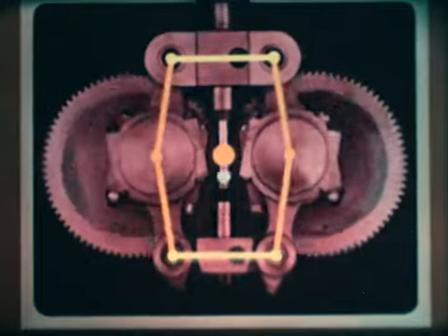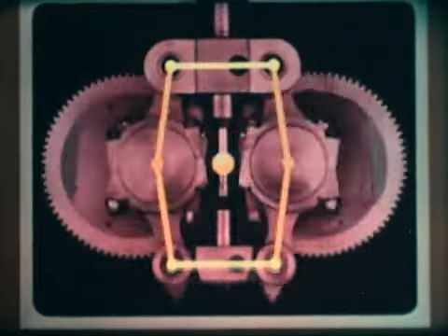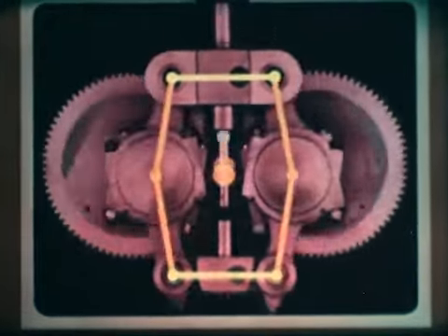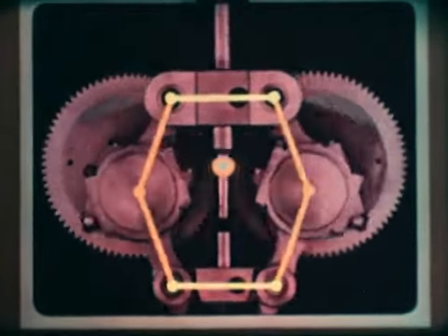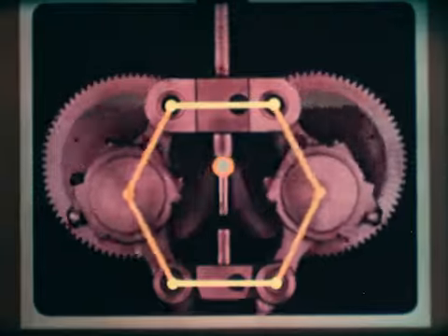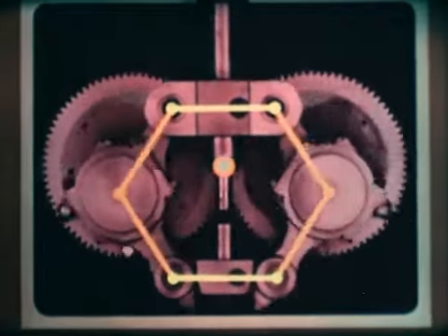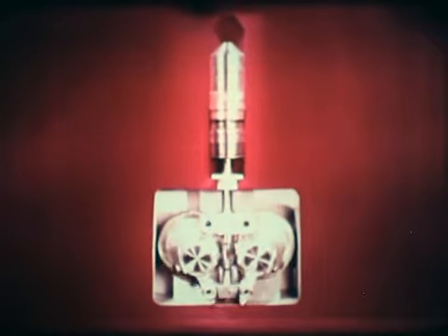The masses of these counterweights can be evaluated so that the center of gravity of the whole system remains static. This means that this single-cylinder hot gas engine is inherently balanced. Perfect balance means complete absence of vibration at any speed.